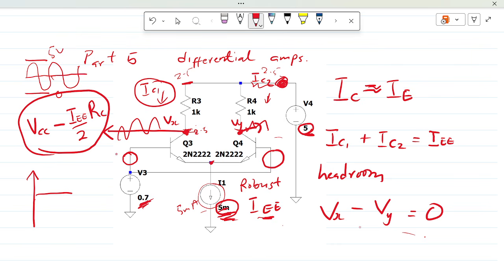So this time around, the microphone signal that was introduced was plus V0 sine omega t, and here we had V0 sine omega t plus a phase shift of pi or 180 degrees, or you just put the negative in front of that as we did, and we saw the differential output.